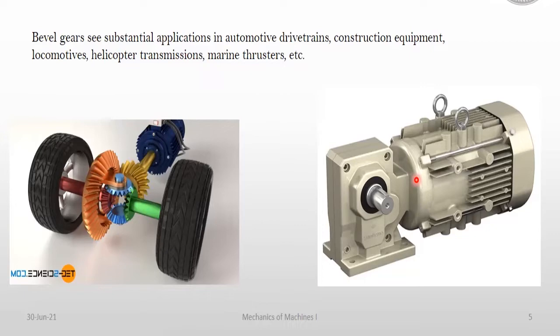Then they have to use the hypoid gear drive. They can't use spiral or straight bevel gears, because the two shafts are offset by the application requirement. So they have only one option, the hypoid gear drive.